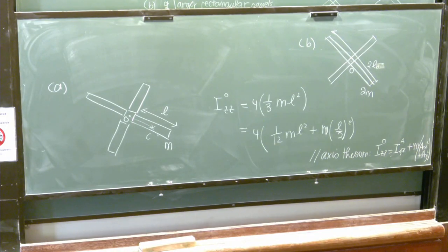Just after leaving the platform, the diver's fully extended 80 kilogram body has a rotational speed of 0.3 revs per second about an axis normal to the plane of the trajectory. Estimate the angular velocity later in the dive when the diver has assumed the tuck position. Make reasonable assumptions concerning the mass moment of inertia of the body in each configuration.